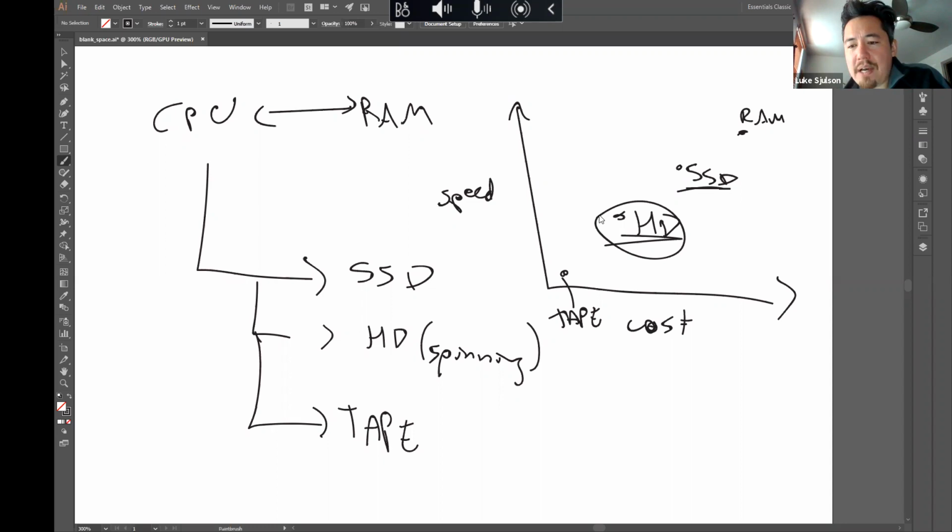We talk about the size of a file, like how long 1 hour of data will be, but you also have to think about the speed of data per second. If you're recording 256 channels at 20 kilohertz, at 2 bytes, then how many megabytes per second need to be written to a hard disk, and will my computer and hard disk be fast enough to capture that? For electrophysiology, it pretty much is.